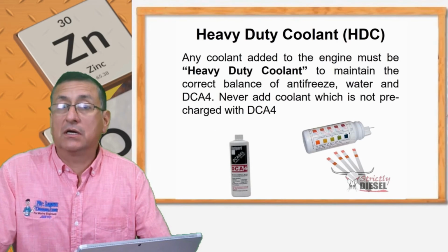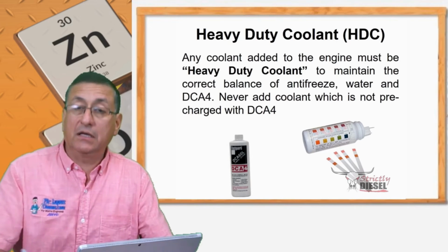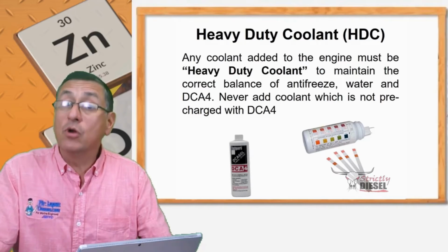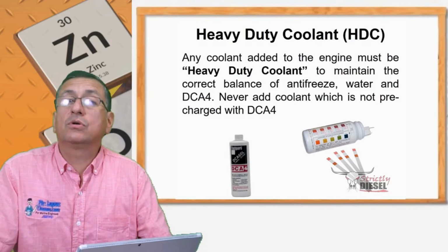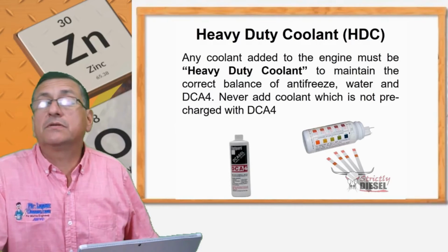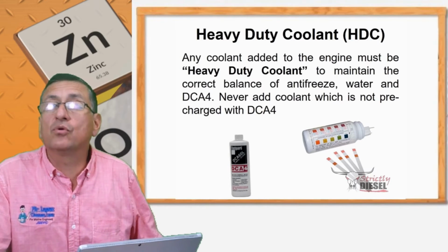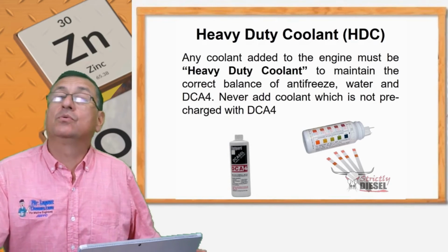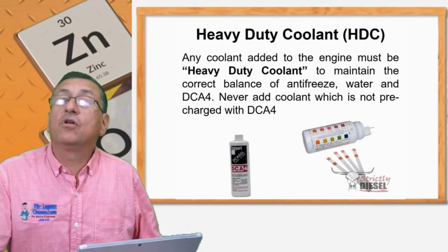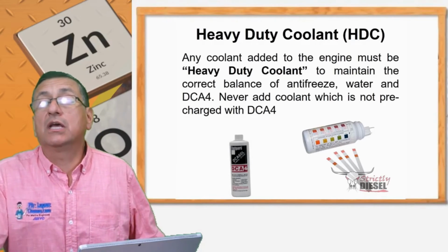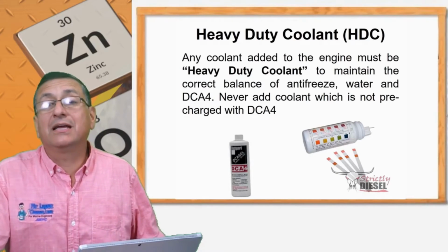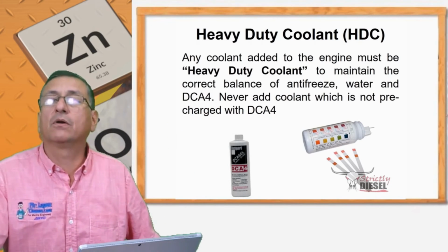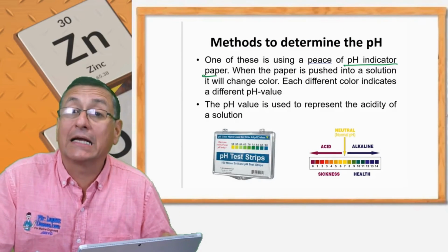Those are similar to the paper strips that you use to check the condition of the coolant. You remember in our diesel course, when you use the SCAs in order to identify if the level of SCAs is good in the coolant? It's basically an indicator of the pH. You remember that one? It's exactly the same as this, okay? In order to check the level of alkalinity.